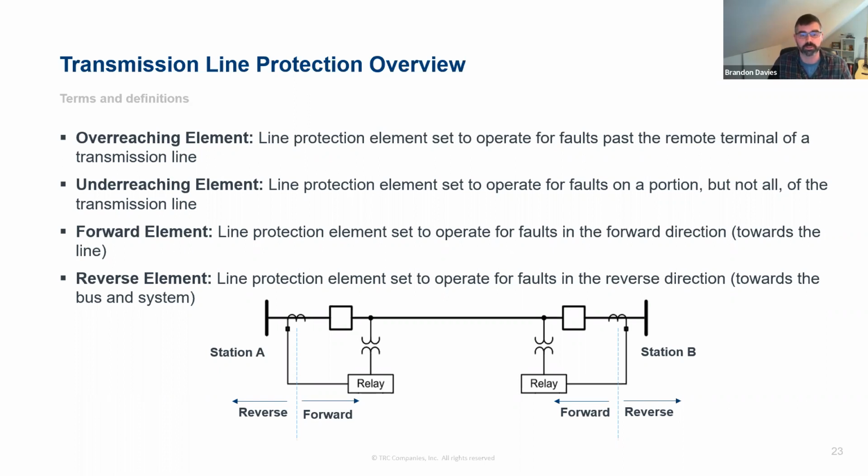With increasing distributed generation and more complex distribution arrangements, that does change a little bit, but in general we're talking about radial protection, where all the fault current is going in the same direction. We don't have to worry about directionality as much because it's built into a radial system.